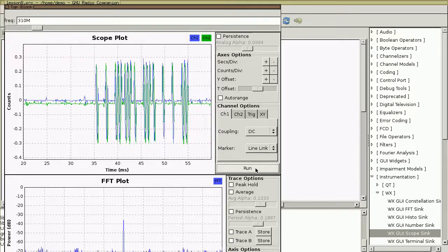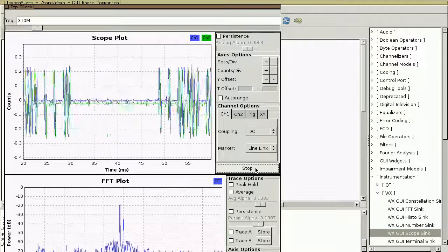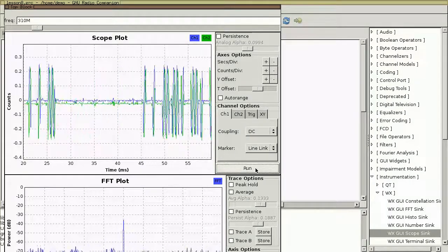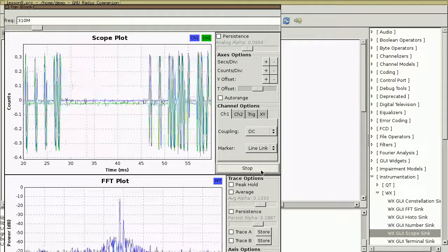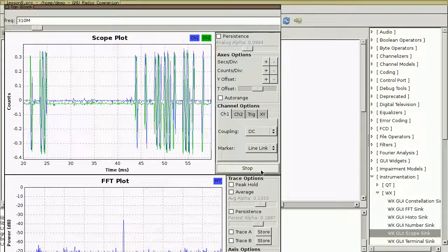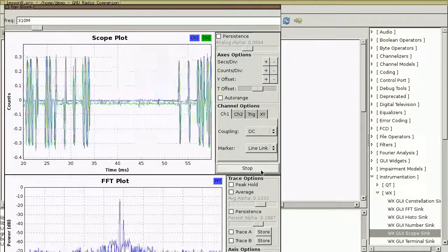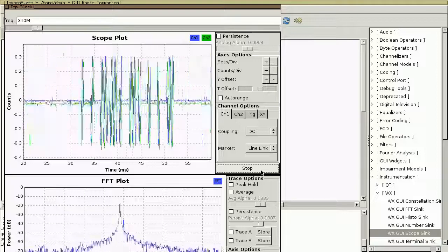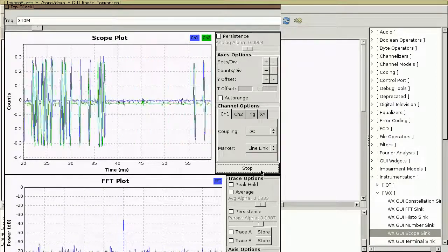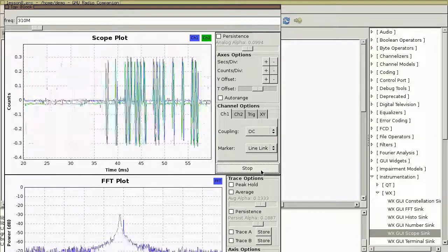And if I release the button and press it again, and run this some more and stop it and try to get that whole set of pulses on screen at once, we see the same exact pattern. Short, short, long, long, short, long, short, short, short, long. The same pattern of 10 bits over and over again in these groups of 10 pulses. This modulation is known as on-off keying. It's the simplest form of amplitude modulation. The amplitude is changing to extremes. The transmission is either on or off, and that's why it's called on-off keying.